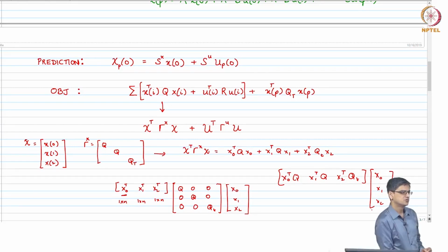That is the objective over here. In MPC, the objective was set point tracking, disturbance rejection or regulation, all 3 objective functions. LQR, the objective is only regulation, okay.